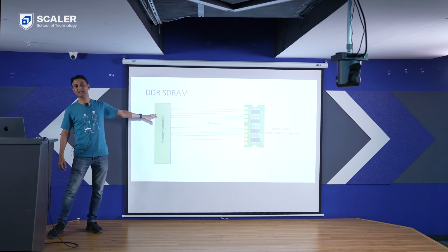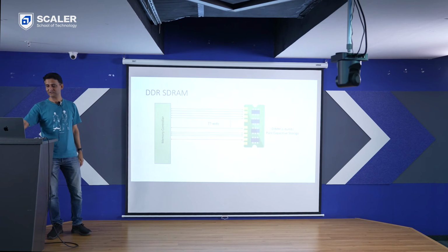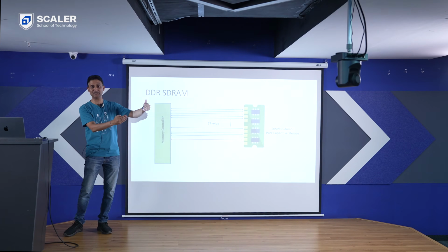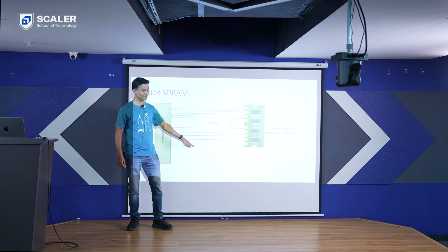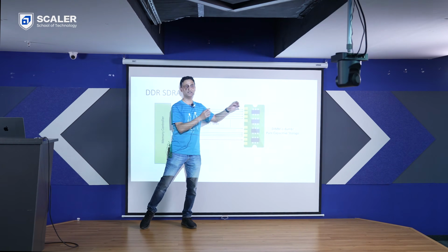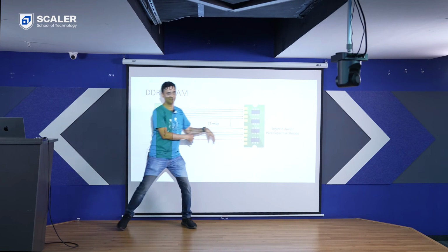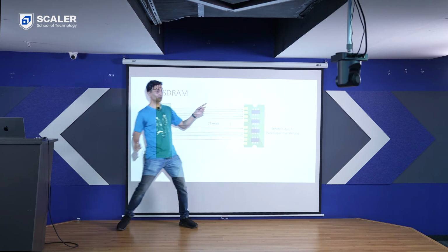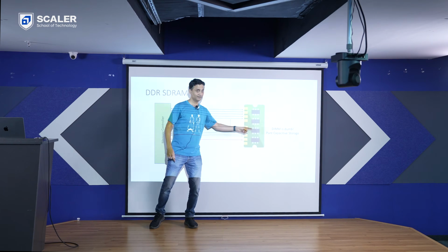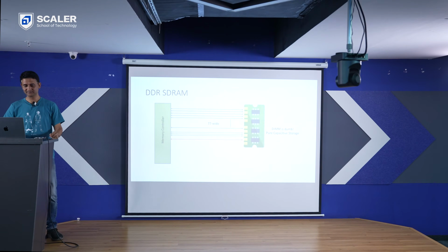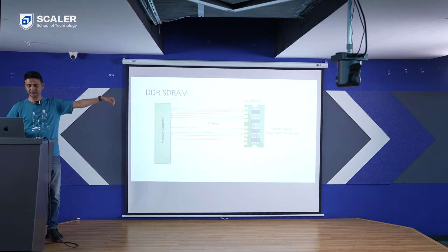This guy is known as a memory controller. This guy understands the layout of the memory. So when you actually plug the memory into a slot, there's a bunch of lines that I've not shown here, through which information about the internal structure, how many rows and columns exist, etc., are fed to this, and after that it is completely this guy's call. So it may distribute 1 byte, for example, amongst different chips. So this guy is intelligent, that guy is dumb.